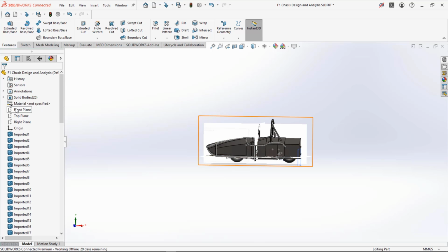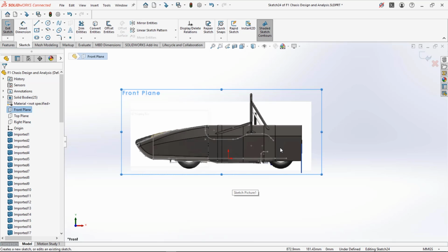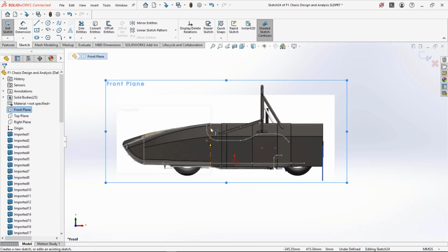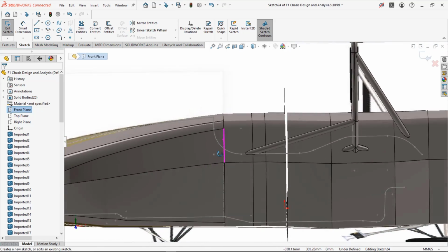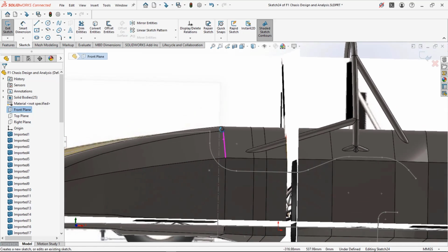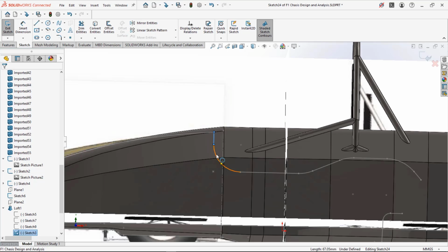Can use the sketch references. I'll draw the cut section area. So this time I won't draw the sketch again. I'll refer these previously created sketch edges as the references here. Can hold the control and select all the edges.